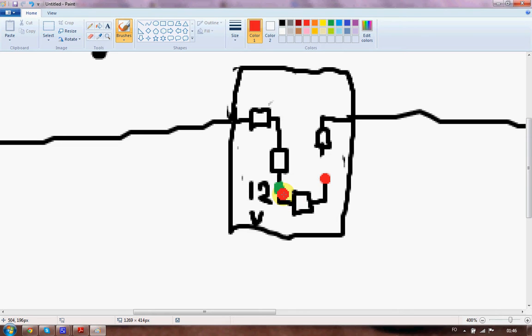So having 0 volts on this green spot implies that there is a break somewhere further back, for example here, or even here, so that the voltage potential can never reach its intended spot. I hope that makes sense for you.